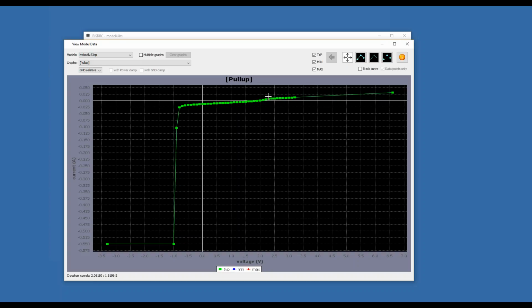There's a bunch of data points from a little bit below ground to VCC, either from their models or maybe lab data. They extended all the way out with that data point, and here it looks like they tried to extrapolate where the clamp curve would be, down to minus VCC, when they might not even have had to. So this might potentially be a problem.